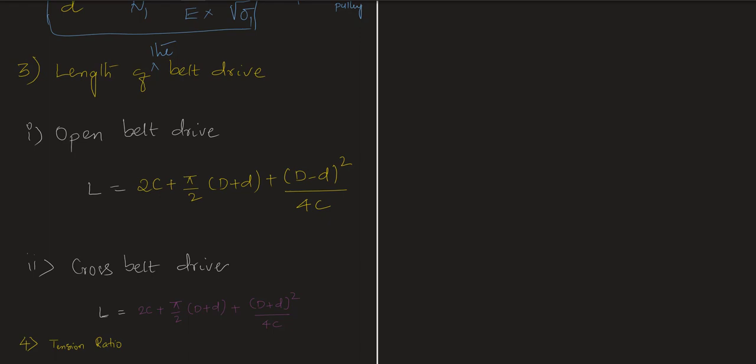First you will be cutting your required length, then you will be keeping it on, and the two ends of the belt are joined in order to make the belt into a loop. Let us say we have a driver pulley here and a driven pulley here. First we calculate the length of the belt, and then we keep the belt on these two pulleys. Then by using some type of fixing or joining method, like bolting or clamping, we keep that.